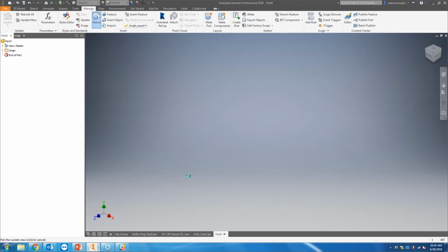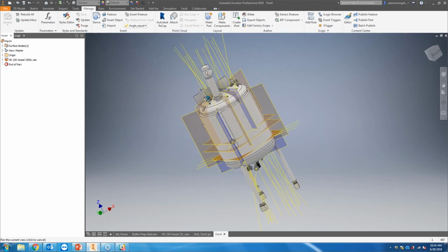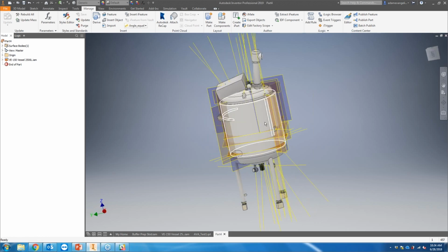Note that after this all loads, you derive the assembly and you still end up with one part, right? You're not deriving an assembly and getting another assembly, like you would get using one of two things: the Design Assistant or the copy design functionality in Vault. So they have different uses.